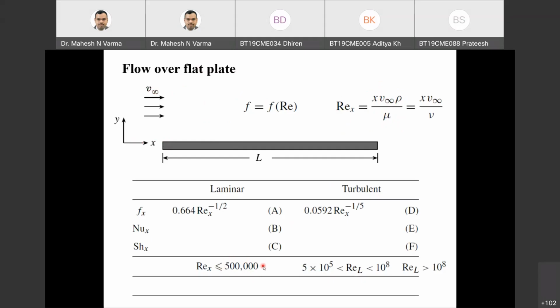As a chemical engineer, having the information that Reynolds number less than 2100 is laminar flow is good, but you must know the system also. It is for flow through a pipe, and all the properties are estimated at average velocity, average temperature, with viscosity, density, and velocity averaged. That is the Reynolds number for flow through a pipe.